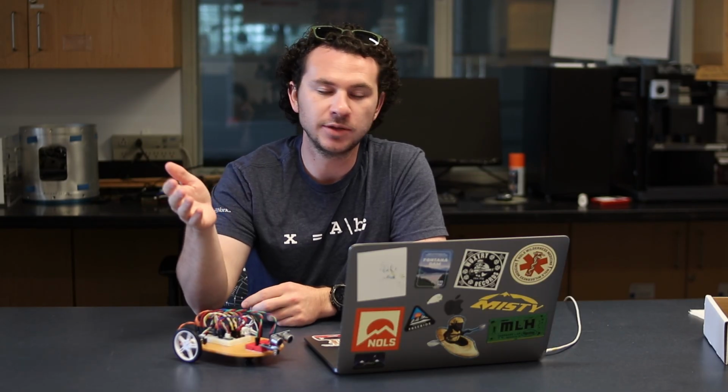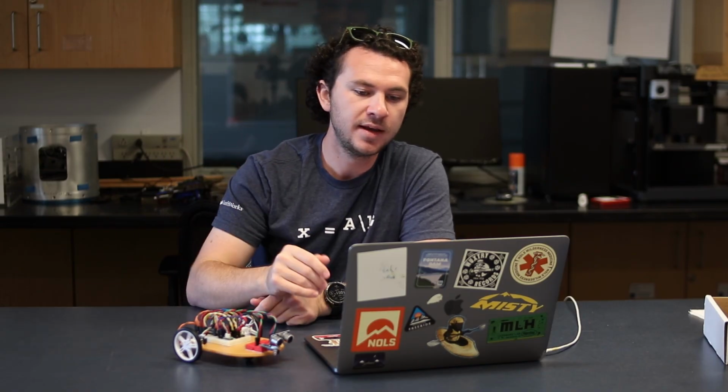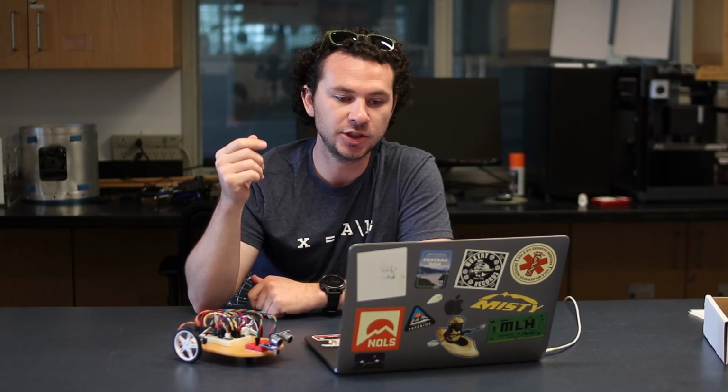Fundamentally, digital communication between processors is all about taking the output of one processor, connecting it to the input of another processor, and agreeing on the meanings of different logic levels and timings. Digital data is represented with a base 2 number system, where each digit or bit can have a value of either 0 or 1. It's easy enough to assign a value of 0 to a low pin voltage, or 0 volts, and a value of 1 to a high pin voltage, or 5 volts in the case of the Arduino.